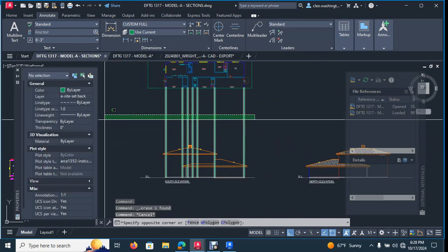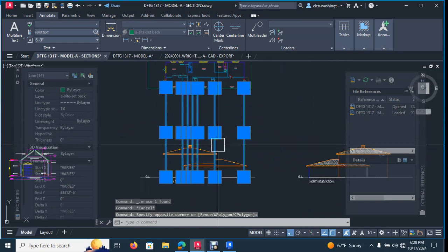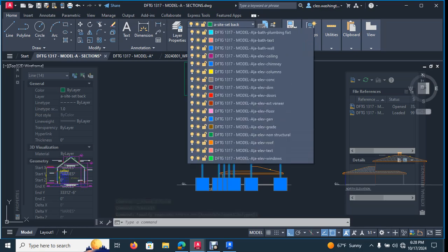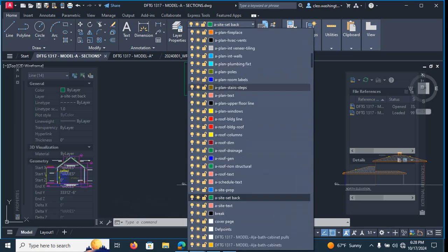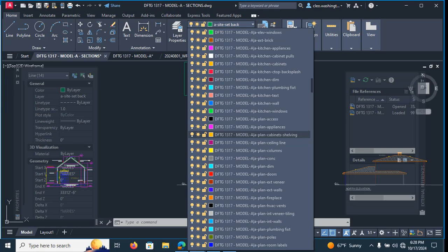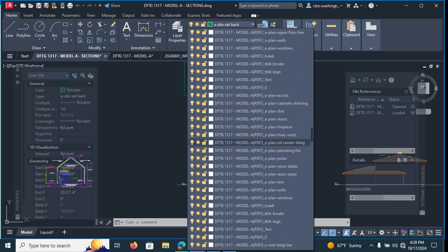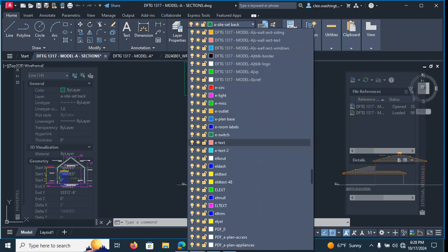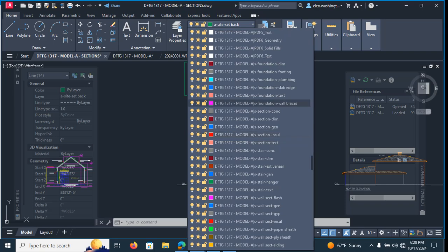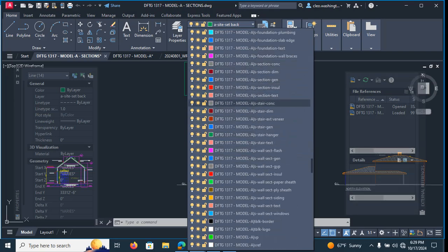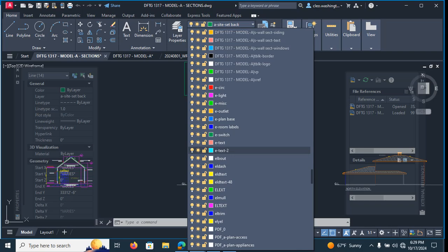Okay, now let's take these lines right here. Let's actually put them on a section layer. So go to the Home tab. We have it on the site layer. So there's a section layer. Let's see, I think I saw the section layers below the imported layers. If the layer is grayed out, like these are just layers that import with drawings that you bring in. These all white layers came in with the PDFs, if you remember. And these layers right here that are grayed out came in with the Revit file that I just brought in.